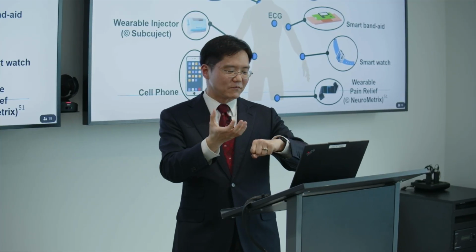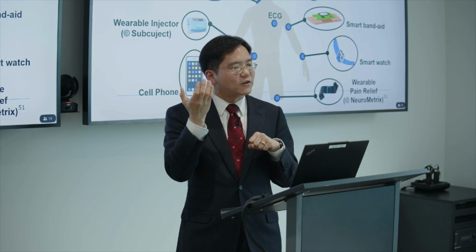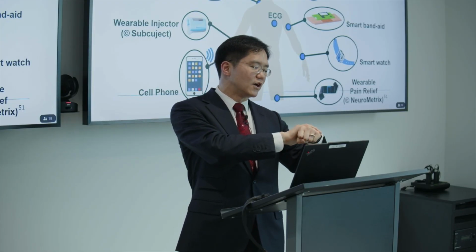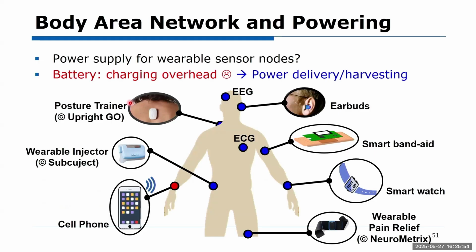For example, the battery is the bulkiest part in most wearables. Because of that, in the patch with the wearable, you're having some inertia from the battery, which makes the sensor interface circuit suffer much bigger motion artifact than before. And this is a big problem. If you can actually trim down the volume of the battery, or if you can actually remove it as a whole, that's the best story. All sorts of wearable sensors are using batteries by default.